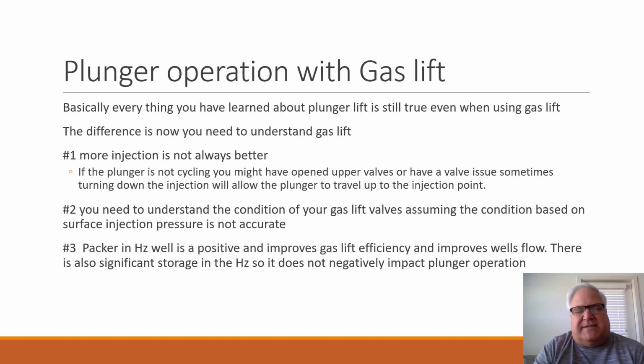Then the very last thing that's really interesting is packers in horizontal wells is actually a positive. A lot of times we've just put packers in wells when we're doing a gas lift conversion and planning on starting up a gas lift on a well that was flowing naturally. We put the packer, almost identical completion except for the gas lift mandrels and the packer. We bring the well back on, and it'll flow another 6 months or a year. And we haven't really changed anything other than the packer.